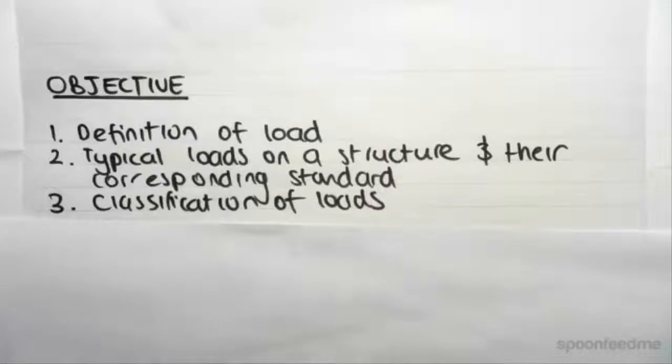Now, up until this point in your degree, you probably would have done a structural mechanics course where we say have a beam or a column subject to some type of axial or UDL or point loading, and normally that's given to us in the question. We have, say, a 14 kilonewton per meter on a 5 meter beam, for example. So what this part of the course looks at, the objective of this entire course, is now to work out the magnitudes of those loads. So where do we actually get those loadings from? Where did we get that 14 kilonewtons per meter from?